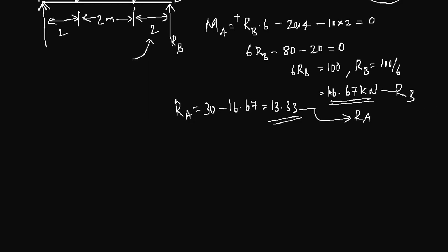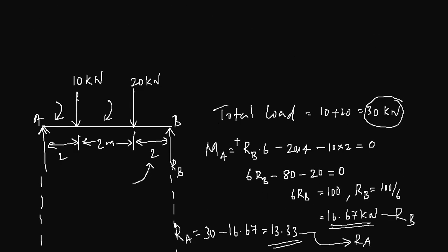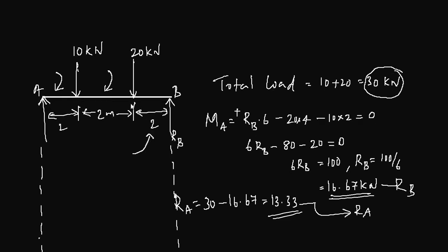Before going into calculating moment, I'm just drawing a line here so that you can draw the bending moment diagram in those lines. Okay, so I'm just leaving that area vacant so that you can do the analysis or draw the diagram there. Now the usual method is method of section. So you take a section in between each point of load application. So you take a section here, another section here, and another section here.